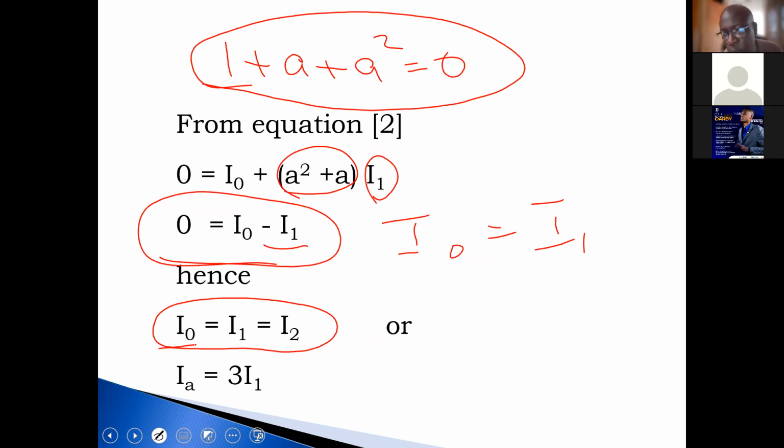We have looked at a load. We have looked at transmission lines. Now, those are the 4 major components. And of course, loads can be static loads, can be rotating loads like large motors. But those are the 4 major components that you're going to have in your power systems. You have your generator. You need a transformer to step up the voltage. You need your transmission lines to take it wherever you want to go. Then you have another transformer, and that transformer takes it into a load.